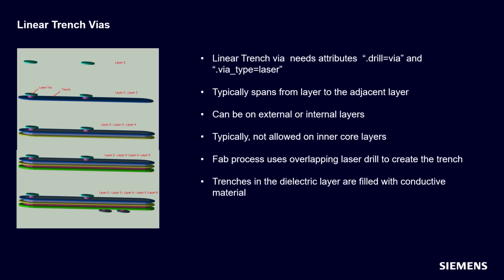Linear trench vias are advanced technology in PCB design. The technology is like the dual Damascene process used in substrate design. Vias designed as trenches serve multiple purposes. They reduce DC resistance by increasing the cross-sectional area of the copper. They provide localized ground shielding for sensitive signals, and they act as thermal heat sinks embedded within the board and offer mechanical reinforcement around mounting holes.